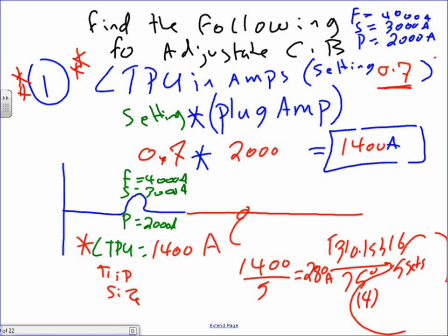Each one of them is 300 kcmil THHN. Now, if you parallel 6 sets, would it be wrong on the test, guys? When you parallel, you want to hover around 400. Adam might parallel 4 sets and end up with, say, a 500 kcmil conductor, and that's fine. So that's how you size your conductor. The most important thing, guys, is sizing the conductor based on the long time pickup.